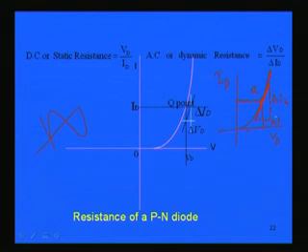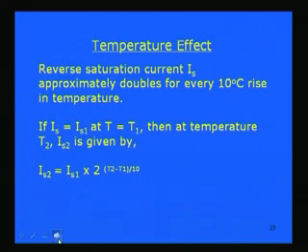That is, dynamic resistance is given by del Vd by del Id, called dynamic resistance or AC resistance, because you are operating the diode under a signal which brings the current to this point and voltage to this point, as well as the other point, because it is a sinusoidal or varying voltage, so we have to find the dynamic resistance of this diode.